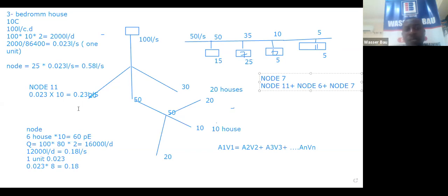If I produce a table for 10 houses, 20 houses, 30 houses, then if it's between 20 and 30 houses, I'll use the point value, and if it's between 10 and 20 houses, I'll use a point value, just like we do in structural design. Those of us who are civil engineers, when you do a 5-meter beam and a 6-meter beam, we all know that we just go for the parameters for the 6-meter beam and use them on the 5-meter beam. That could be a little bit of over-designing, but it is for ease of calculation and for speed.